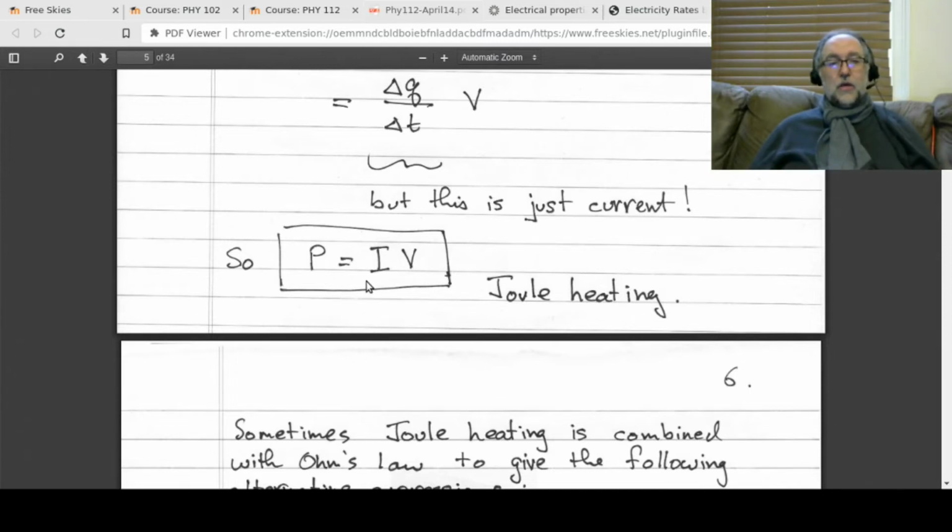That's coming from the Joule heating. So you've got so much current traveling through that tungsten filament, and there's so much voltage across it, because the tungsten filament has some resistance, so there's a voltage drop across the filament. You take the voltage, multiply it by the current, and there's the power that is being dissipated as heat. Okay, so there you go.